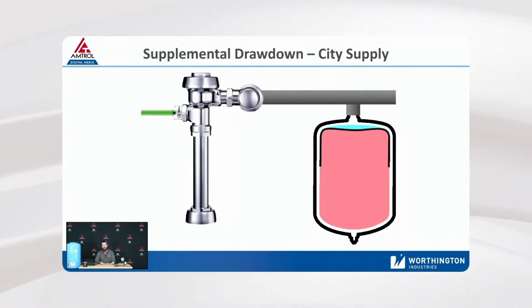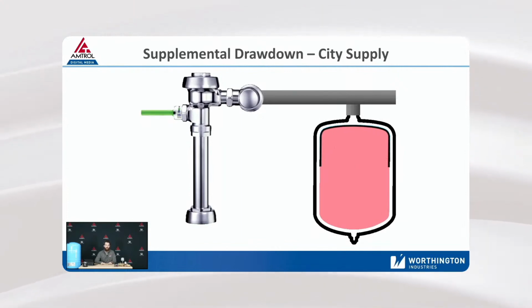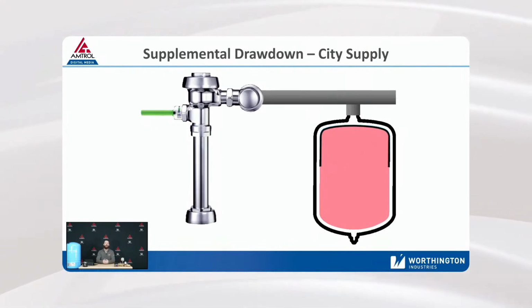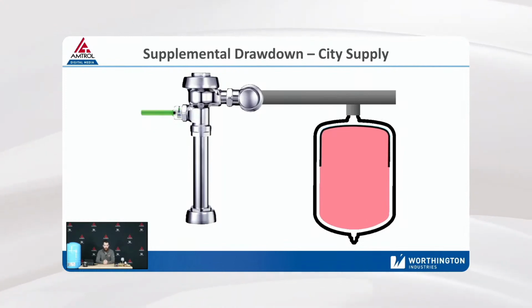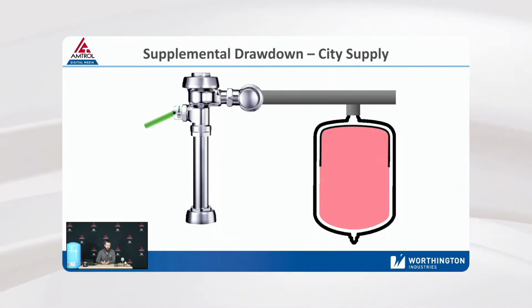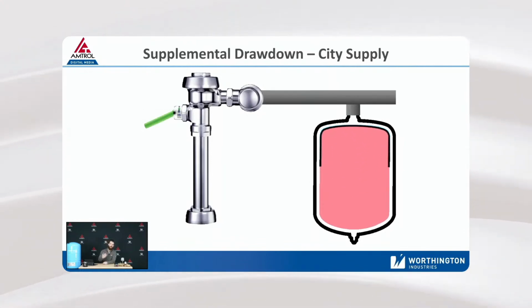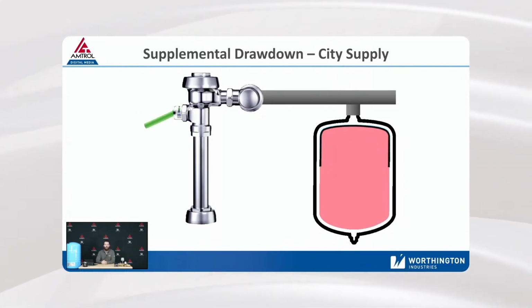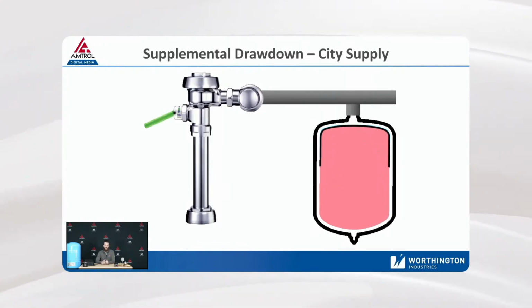So those formulas that we showed you on those prior 2 examples, those would size almost any system I can think of. Most questions that we've run into, most different sizing scenarios, those are the formulas we've used. We've gotten them a tank, we've gotten their problem handled. But hopefully this illustrates how that tank's going to function in its lifespan. It almost functions like a thermal expansion tank if you really think about it. When the system's closed loop, it's going to fill up with pressurized water, and then when the system opens up, it's going to discharge itself. So obviously we have some experience there as well, so that's why we're able to work these tanks into all those niche applications.